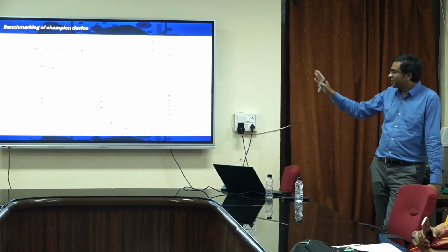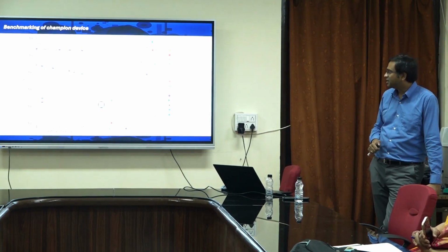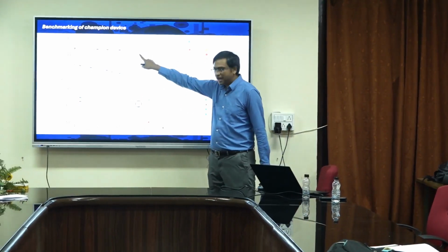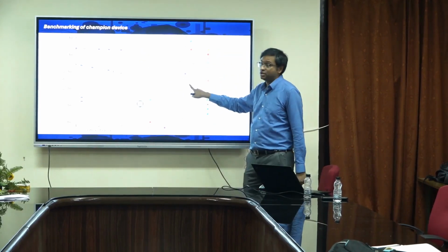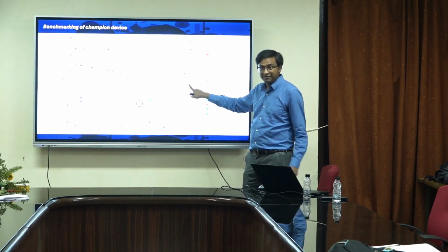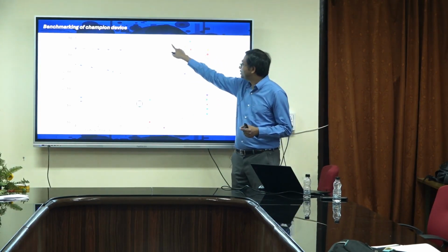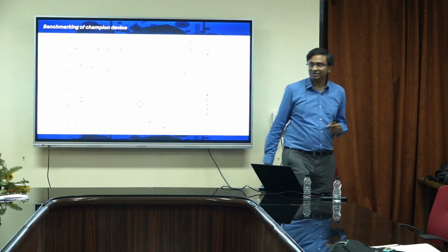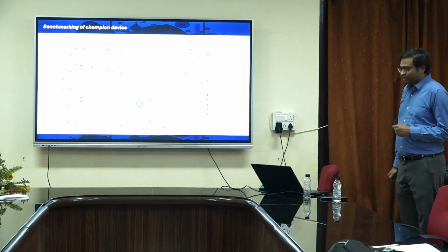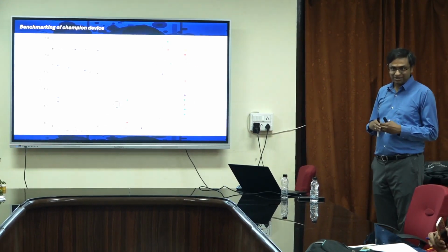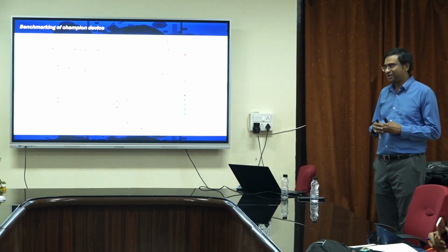Okay, and we are able to get to very high performing devices. Specifically, this is the one I was talking about: high on current as well as high on off ratio. That was our main objective, and see with NO doping where we are compared to the rest of these. So the P-type FET also appears that we are close to solving the problem.